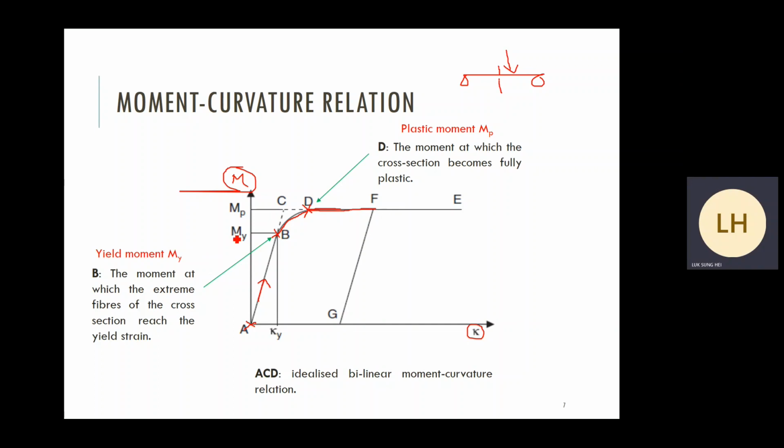You can also understand the behavior using this overall moment-curvature relationship. If you like, you may also map the previous stress profiles onto different regions. Here is the elastic region. Here is the elastoplastic region. And finally, the fully plastic condition.